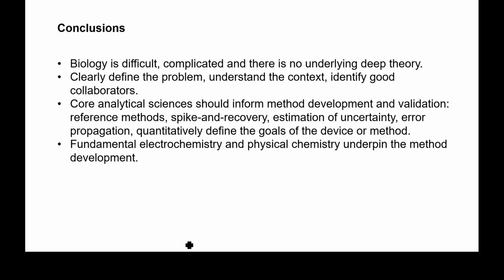Consider using spike and recovery. Do a realistic estimate of the uncertainty and error propagation. Prepare to be disappointed. And quantitatively define the goals of your method or your device, so that you can do evaluations as to whether or not this thing is even working.